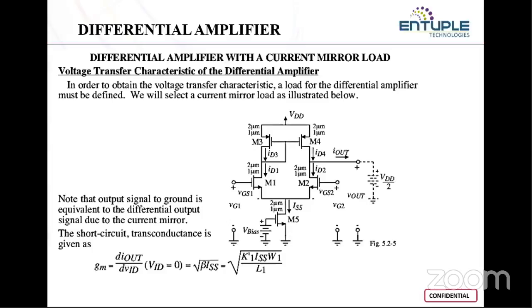The bias is connected to, yes. No, the bias is a voltage bias, but I think it is a current source. Current sourcing or sinking? Since it is biasing in a differential amplifier, it generally means current sinking, right? Yes, exactly. Okay, so let us see how to do that.